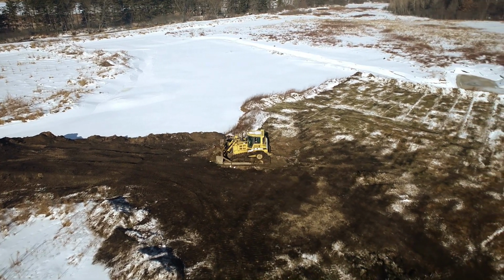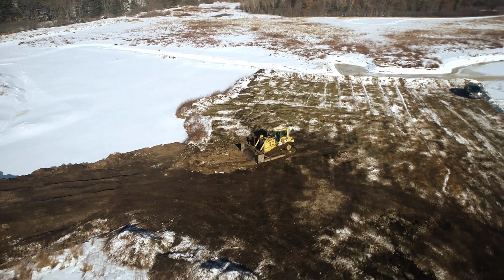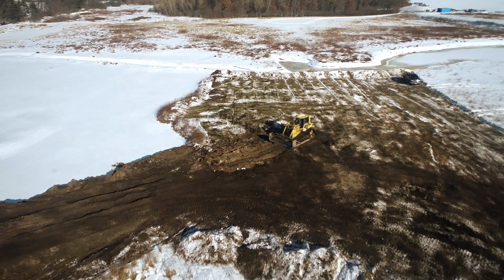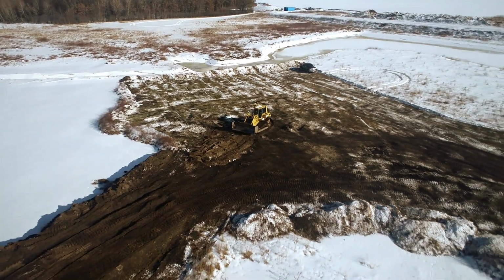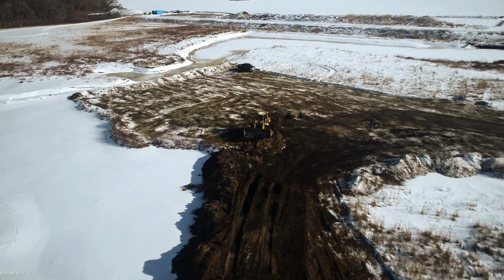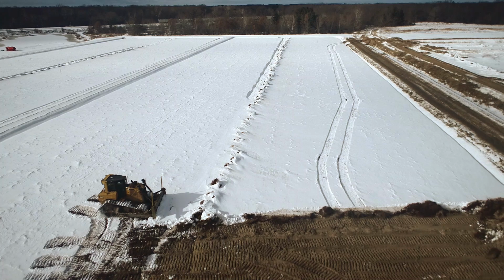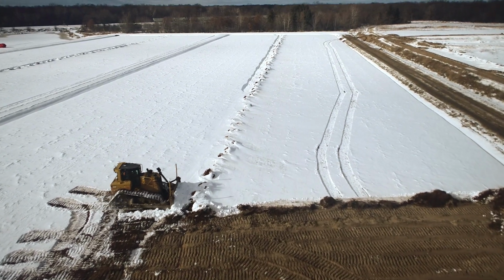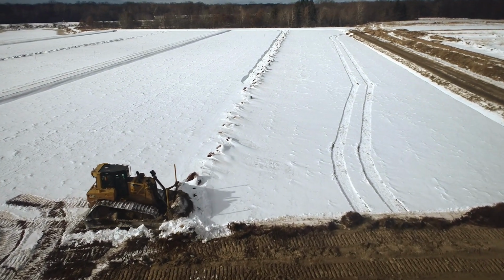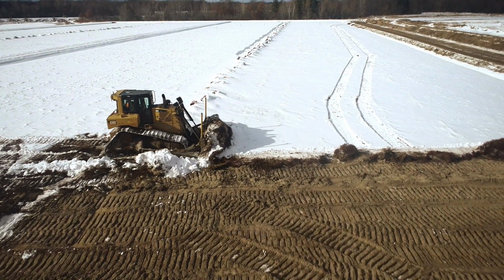When encountering large frost lumps, push them out of the way. Do not turn the dozer while the ripper is penetrating the ground. Only rip in first gear. Prior to exiting the cab, check the controls and be sure that they are in neutral position, and the blade is lowered to the ground. The ripper blade shall be placed onto the ground if the operator exits the cab.